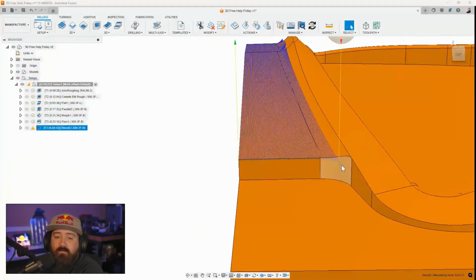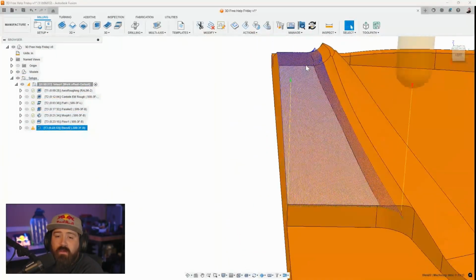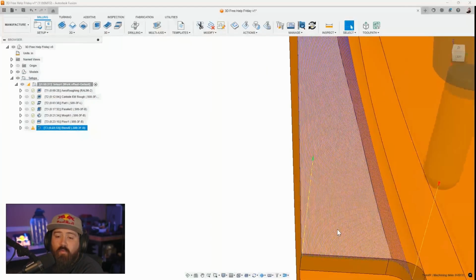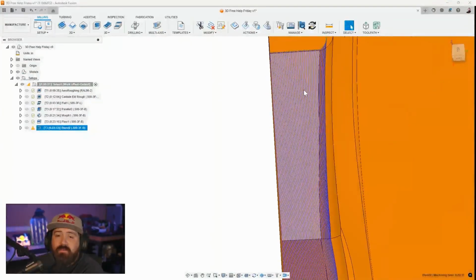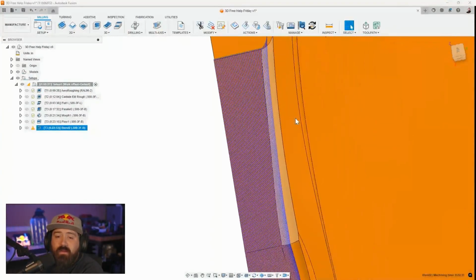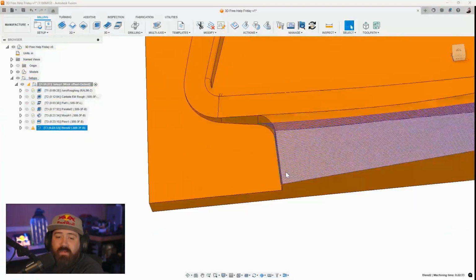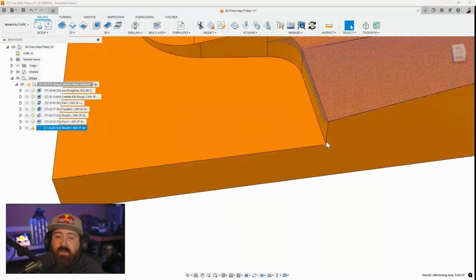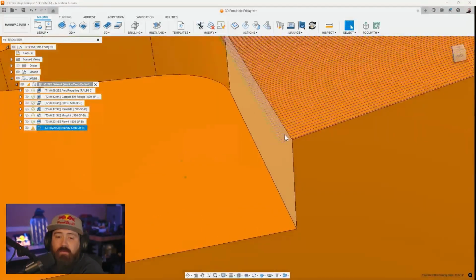We have one lead on. We have a really smooth start. We have a blending or morphing toolpath between those two edges we picked, and we have little step overs on the end. It's getting us exactly what we need to cover the surface. So you can see here we got that little bit we were looking for.